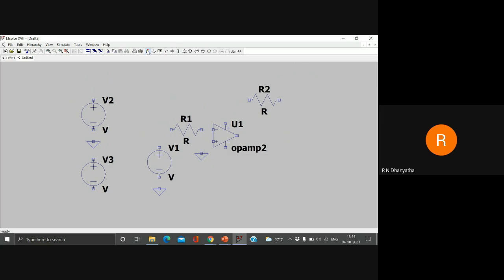Perfect. So click on the wire signal here, and place it somewhere above the second voltage source. So just click on it and then drag the line towards the end, and then just leave it. So make sure that all of the three components are connected there. So two voltage sources and ground are connected together now. So let's leave that aside for now and connect the other components.